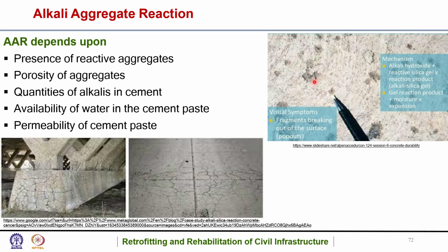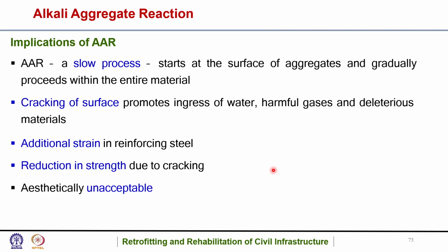And if you can see here, this is a pictorial representation of the fragments breaking out of the surface. Okay, that is the pop outs. That is occurring because of the alkali aggregate reaction. So what are the implications of alkali aggregate reaction?